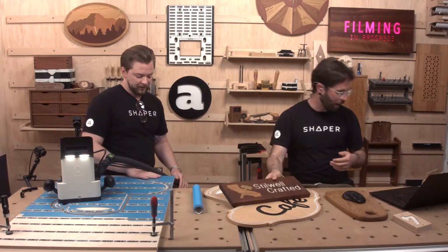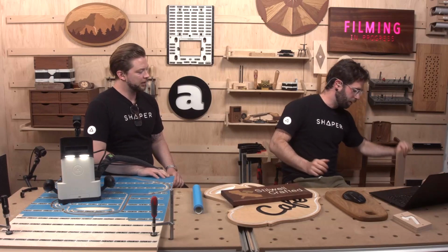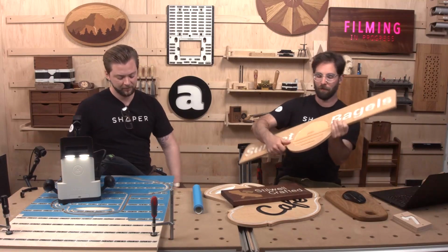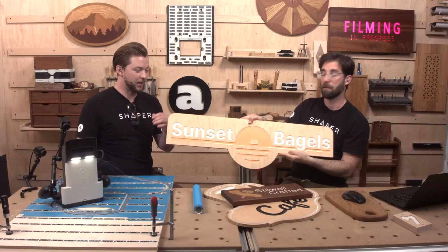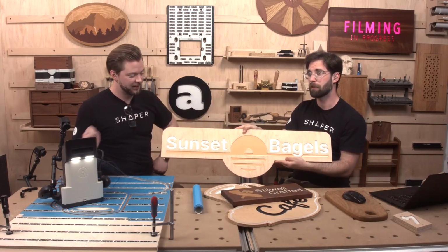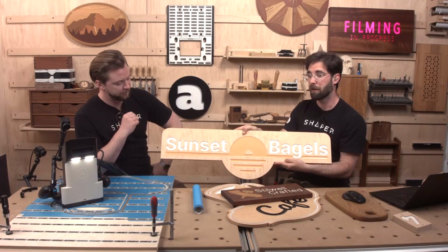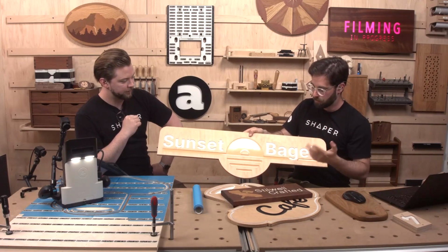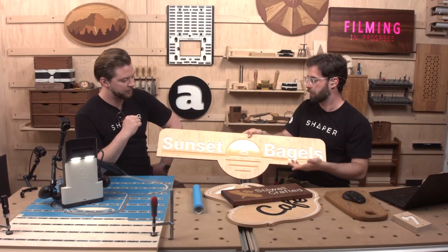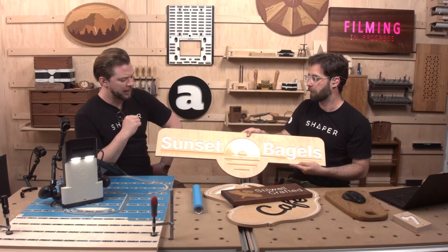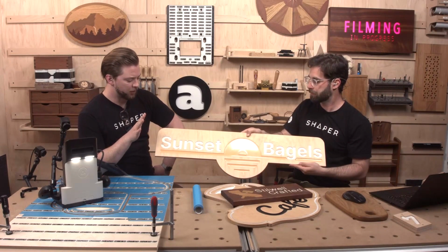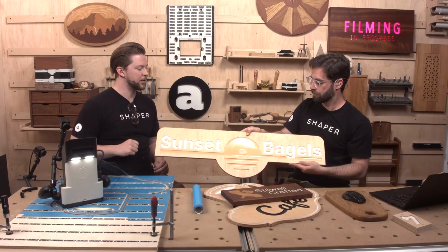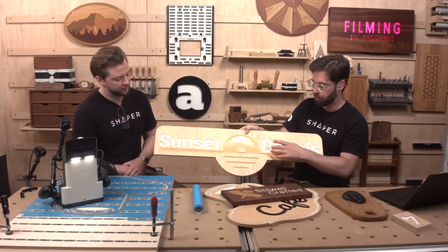All right. We've got more ways to add color. We've got ever controversial, but I think pretty solid for signs, I would say epoxy. Probably the easiest. Yeah. Very easy to mix your own colors with epoxy. Very, very weather resistant. Totally. And what's beautiful about this is that if you apply it carefully, you used a syringe for this, or did you just pour with caution? I think I just poured. This was big enough to where I just poured. Any smaller, you start getting into syringe territory. But you pour with caution, and it's self-leveling, which is really nice.